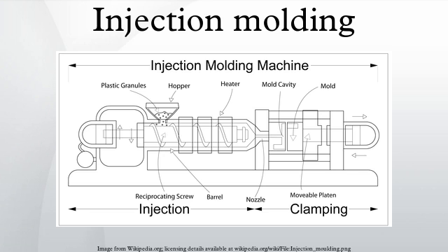Cost. The cost of manufacturing molds depends on a very large set of factors ranging from number of cavities, size of the parts, complexity of the pieces, expected tool longevity, surface finishes and many others. The initial cost is great, however the per-piece cost is low, so with greater quantities the unit price decreases. Rubber injection molding process produces a high yield of durable products, making it the most efficient and cost-effective method of molding. Consistent vulcanization processes involving precise temperature control significantly reduce all waste material.